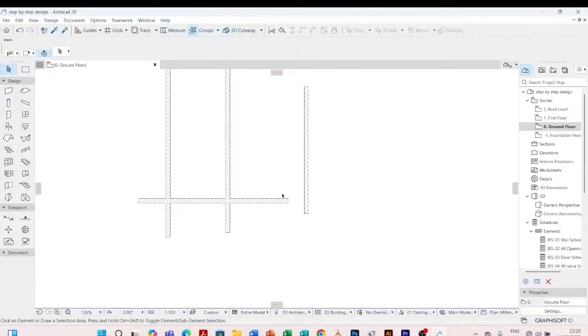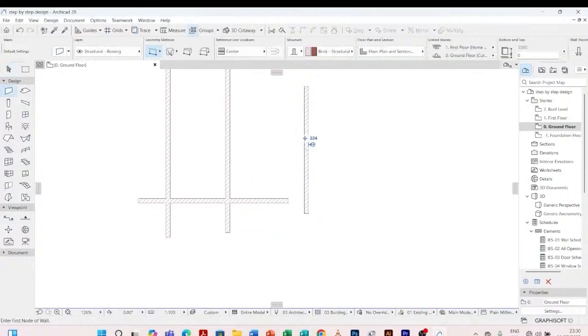They make our work simple. I can come and pick up parameters. So when I come and click on this pick up parameter, or I type Alt C on the keyboard, I'll activate the pick parameter tool. So I can come, I pick this wall. That means I've picked the parameters of this wall, that is all these settings, and now I can draw.